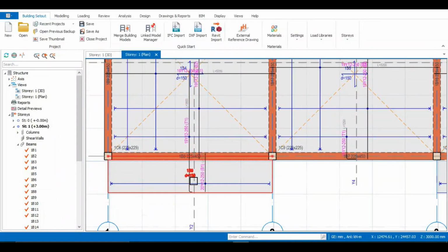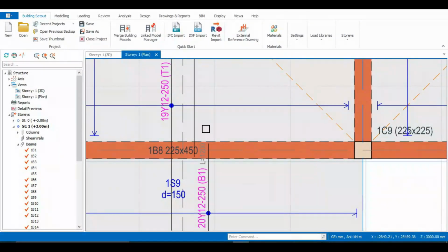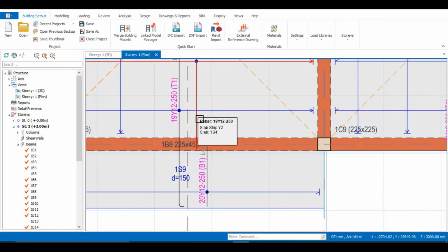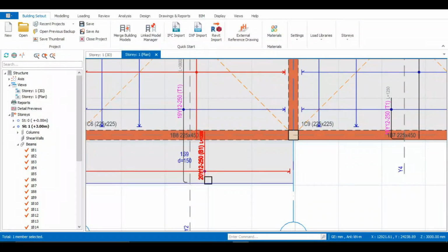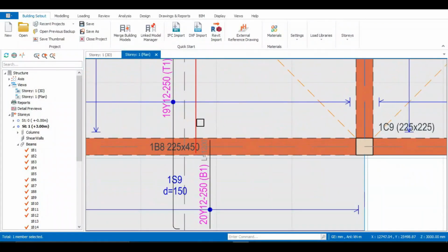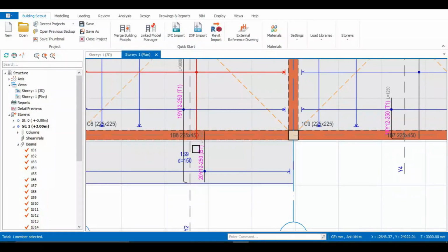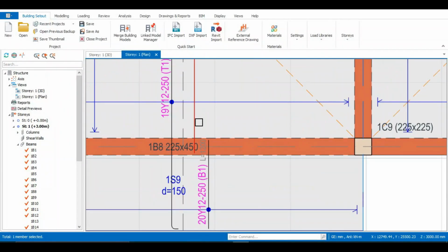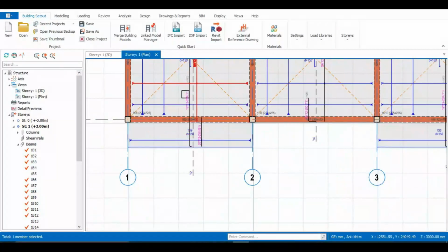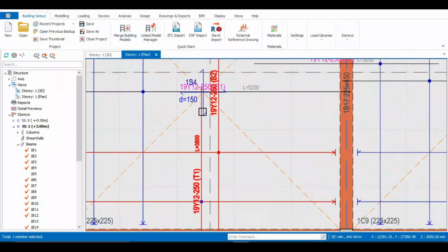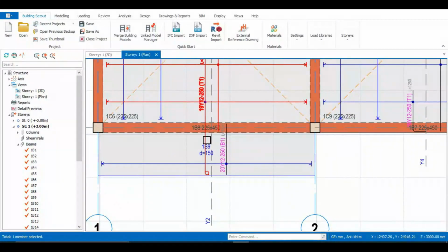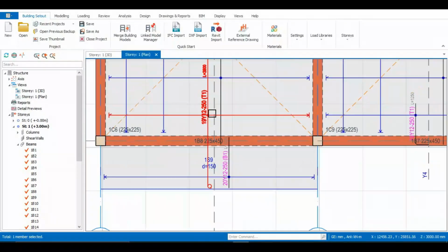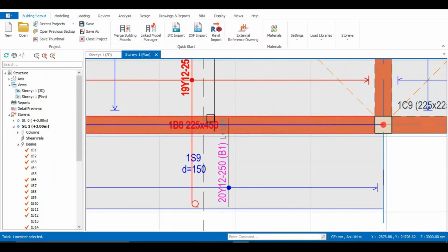But technically on sites what usually happens is that this bar goes from here into the slab, and we usually correct this, or we usually modify this in our AutoCAD when we are doing the structural, after we have gone through Prota details and transferred into AutoCAD. So this particular bar goes into this place, then it now returns into your slab like this. So this is going to be your top, and you see that it has been given the name top here. So this is going to be your bottom. So this bottom can also be this same bar coming right here, then returning.